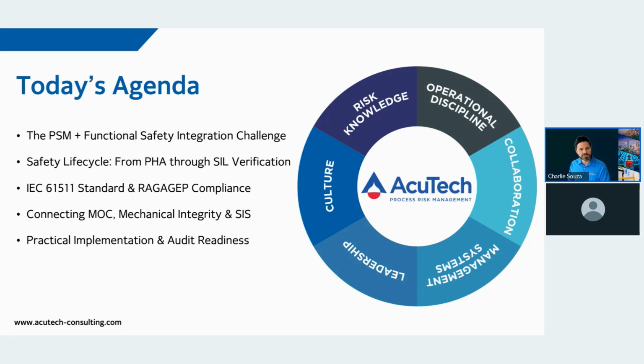We're going to look into the 61511 as a RAGAGEP standard, and therefore something we need to comply with according to OSHA standards, and how we can connect PSM items such as MOC, MI, and SIS requirements from the functional safety management aspect of view together.